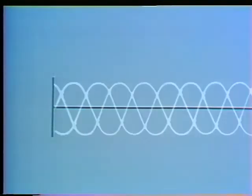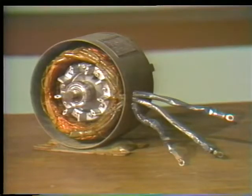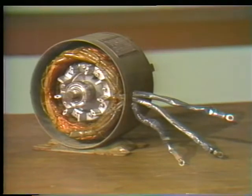When the three sine curves are plotted on the same axis, you can see the relationship between the three currents as they act simultaneously. This simultaneous relationship is found in the stator windings of three-phase motors. In a three-phase motor, there's one lead or wire for each of the three-phase currents. Each lead is connected to coils in the stator of the motor.